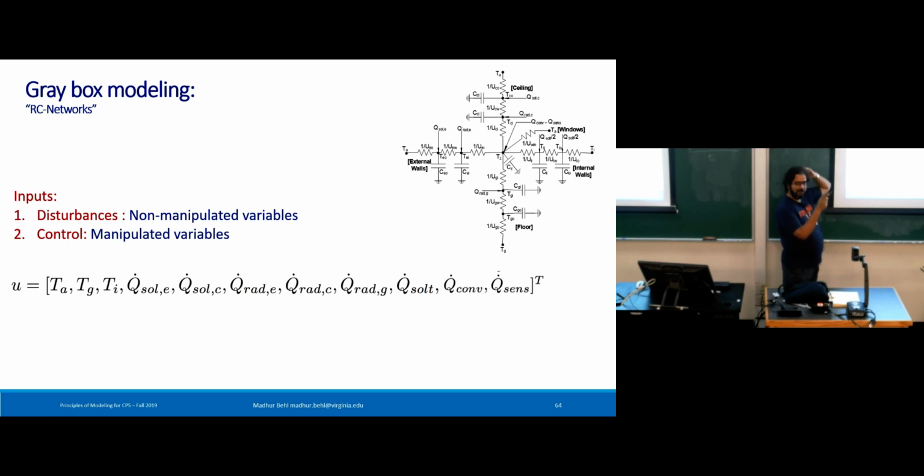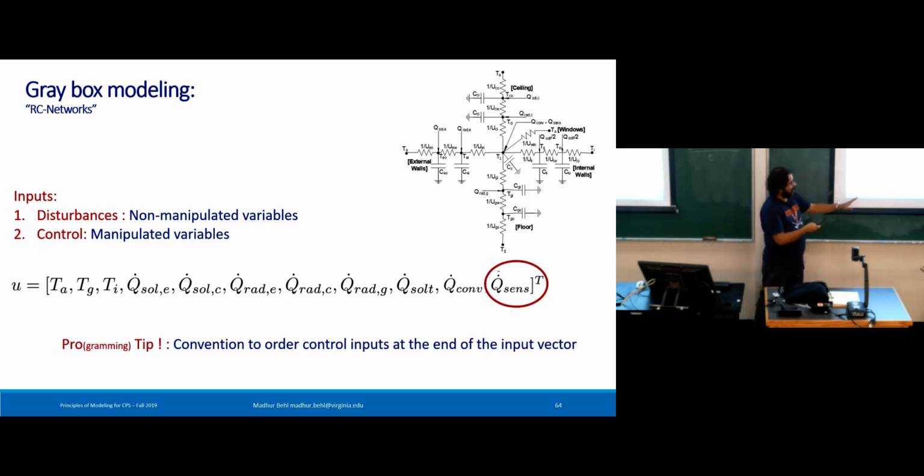Correct, right? So what are we controlling? We are controlling the thermostat. We are controlling mass flow rate, supply temperatures, all that stuff which was the introduction to HVAC. All of that is lumped in nothing but just this one term here. So in fact, everything else in this model is non-manipulated. And we are directly controlling the sensible cooling rate or the HVAC cooling rate or heating rate.